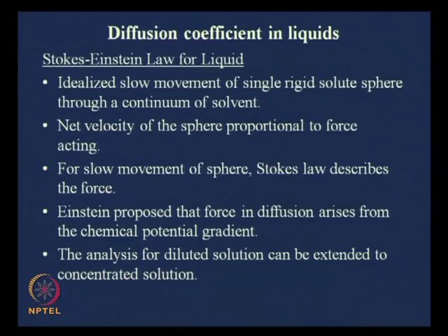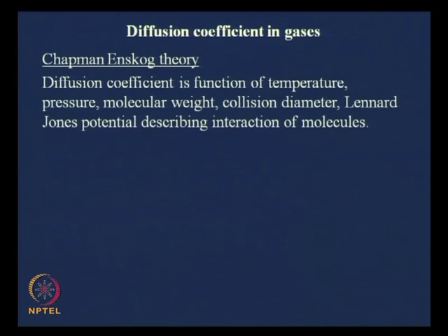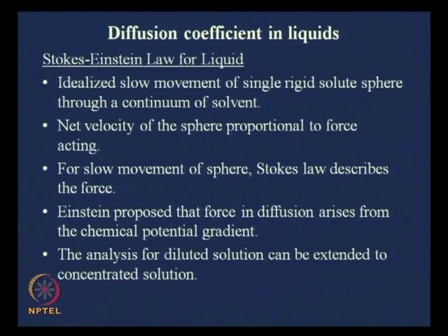Now, when it comes to the definition of diffusion coefficient D, the diffusivities of various materials are available in various handbooks. But if I get into the theories of it, there are two established theories which define the diffusion coefficient for liquid and for gas. For gases, this goes by the name Chapman-Enskog theory, and for liquids it is the Stokes-Einstein law. You can refer to any standard textbook on transport processes. It need not be microscale, because the diffusion coefficient is a very general topic.